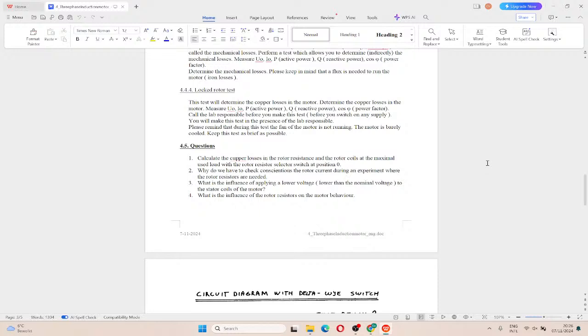Friction loss. So what we basically need to do is use the whole power consumed minus the iron loss. You cannot directly measure it. Yes, we use the total power minus the stator loss. So basically we don't need to short circuit.